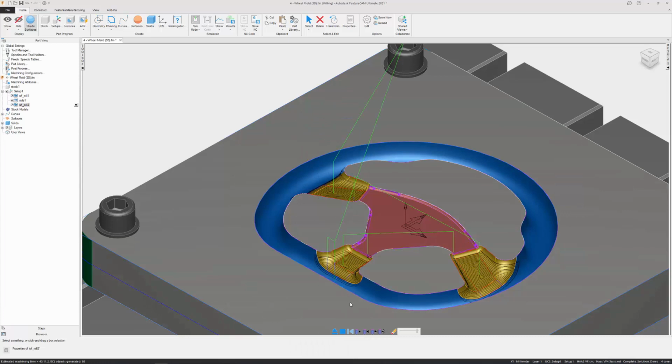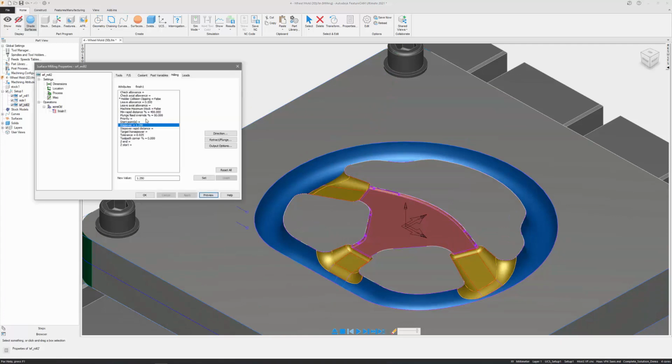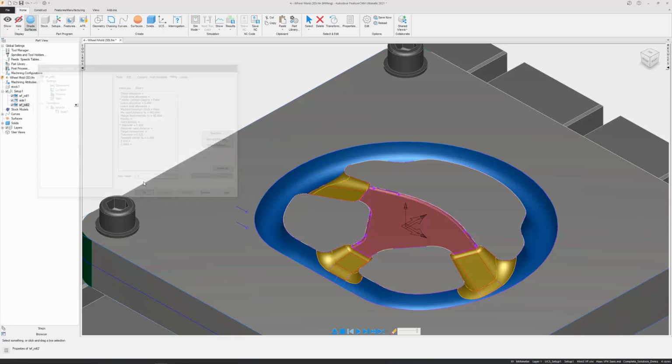And yeah, so I like the toolpath here, but I'm just going to reduce that step over a bit. 1.25 mm isn't the greatest surface finish. I'll get maybe 0.5 millimeter there. And I'm not going to preview it right now just because of the calculation time.